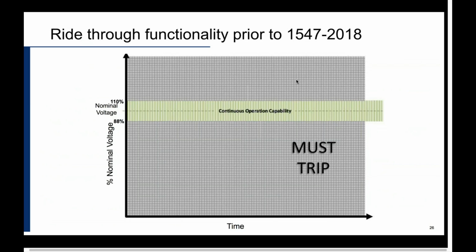This is when the voltage ride through happens. That means when there is an event on the system, could be a fault, could be a tree falls on a line, or whatever could happen. When there's an event on the system, what should DER be doing? In that sense, what was expected out of these DERs before the recent update on 1547?